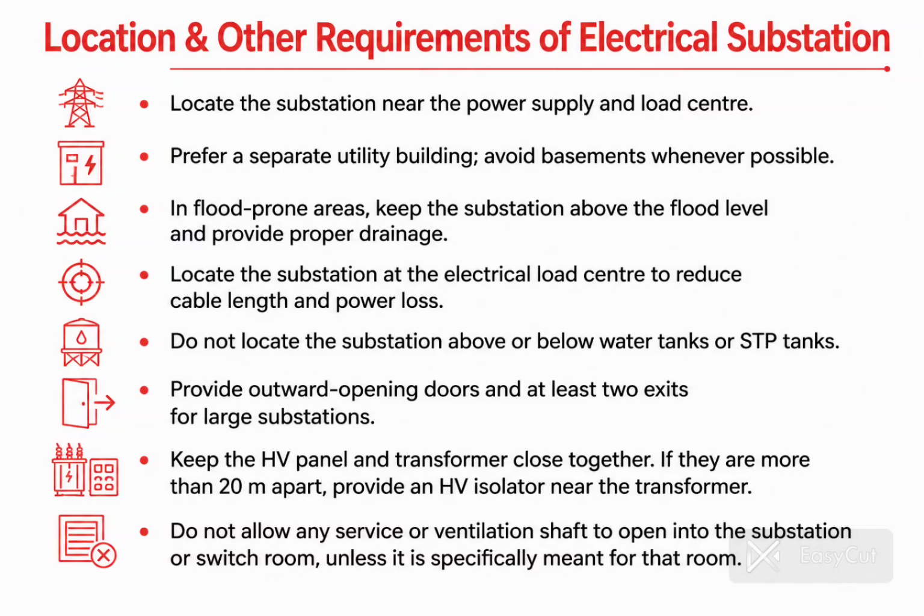Then the fifth point is do not locate the substation above or below the water tanks or STP. Yes, we cannot keep the substation above or below the water tanks, because leakage chances are there for tanks. So we should not keep the substation near, or even below or above, the water tanks.